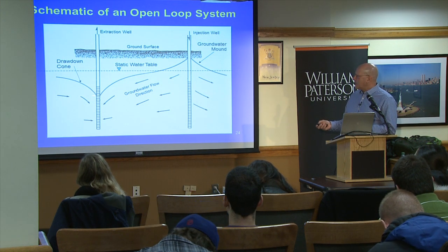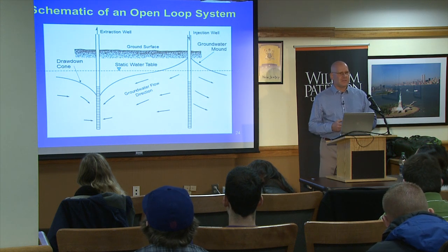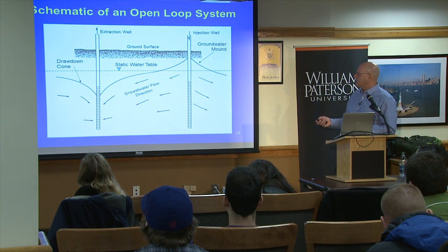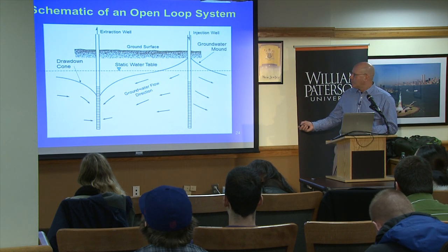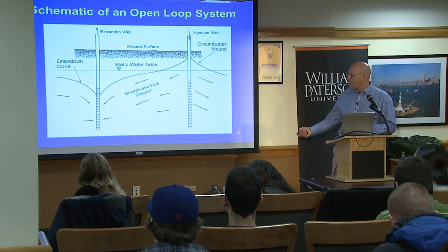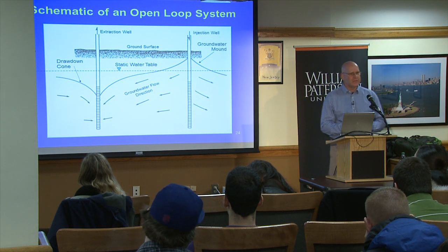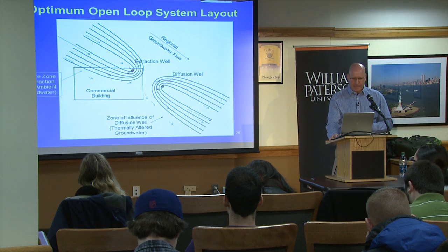We have to evaluate and know this relationship of how much water is going to draw down and how much is going to mound up. We can't just go ahead and install these systems without having a very good idea. In this example, what if the water was to mound up and start bubbling out of the ground? That would not be good. Or what if as we pumped, we drew the water below the pump intake? Also, that wouldn't be practical. So there's a lot that goes into these open loop systems.